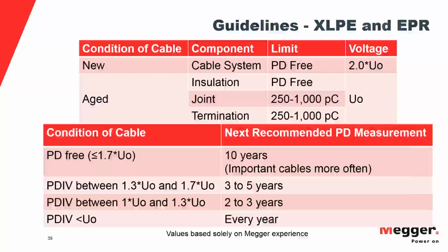So to get exactly 60 hertz frequency out of a damped AC, you need a pretty long cable, something nearer the longer lengths that this is capable of testing. As the cable gets longer, the frequency of oscillation gets slower. So when we say 500 hertz, that would be on your very short cables, like those 200 meter cables without the support capacitor might be oscillating in the range of 500 hertz. But a couple of kilometers long might be in the range of 60 hertz or something.